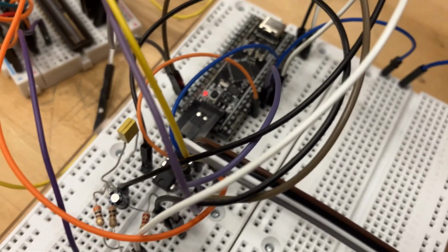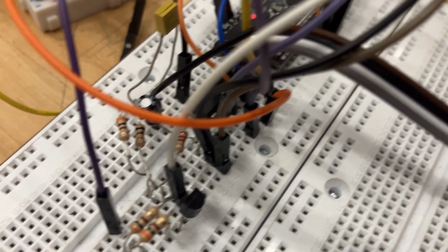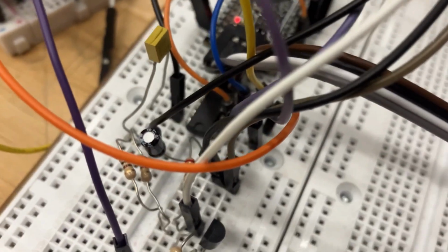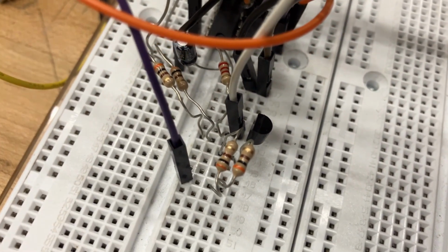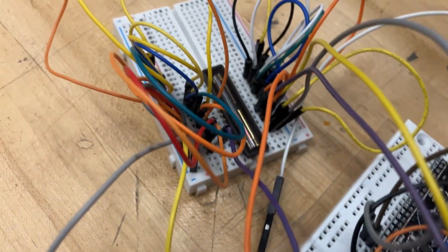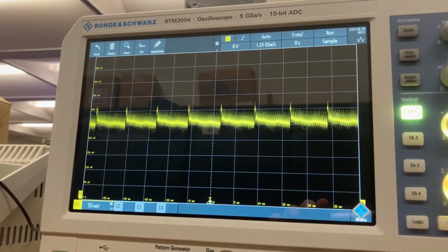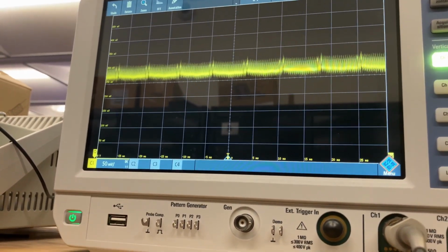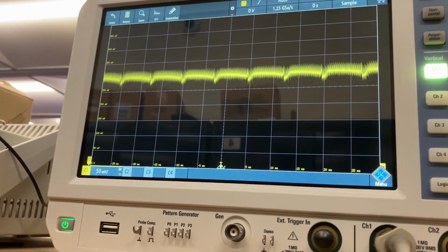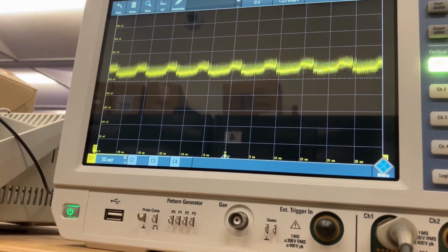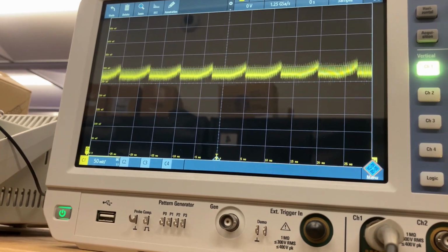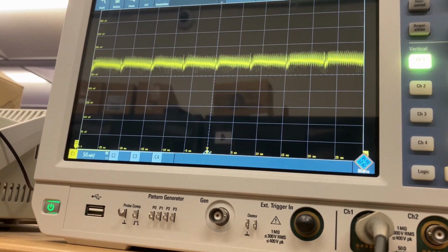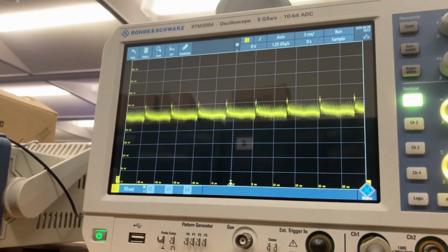Here we're showing the CCD and STM boards. You can see the hex inverter and capacitors and resistors all used to clear the input and output signals of both devices. Here we have the CCD with each non-STM port connected to ground. And you can see the output signal of the CCD through the oscilloscope. The peaks every 7.5 milliseconds are the start and end of each frame. And the fluctuation there is me moving my hand across the CCD from start to end, which you can see in its respective location in each frame.